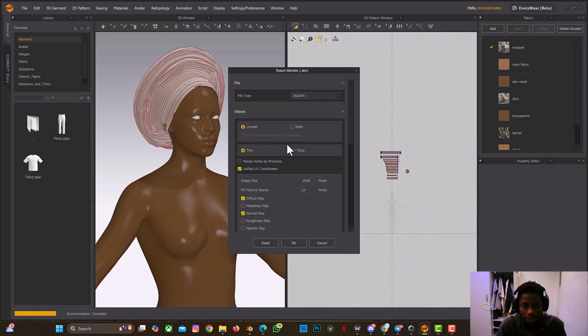So I'm going to change this to tick. Don't worry, you can always uncheck this, or you can check everything, your choice. Just uncheck it, don't touch anything. Then you can set the pixel to maybe 4K, 4096, if you want a better, high quality texture. I think 4096 is what I used for this animation. So 4096 pixel, select OK, and that's all, and then we'll cancel.